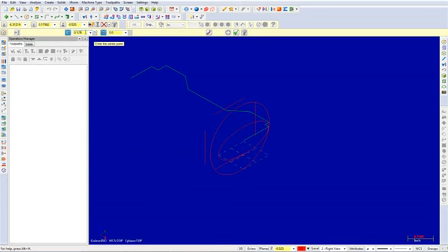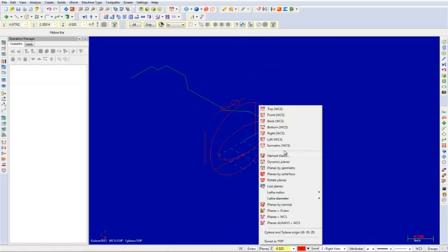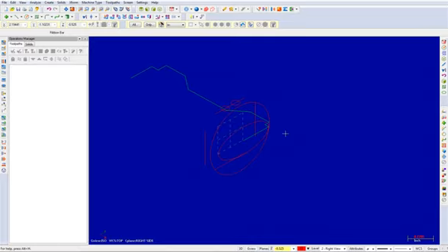Click on the diameter icon to lock this value as shown. Locking this value allows us to create multiple entities of this size. Then pick the 2 line endpoints as shown and select the OK button. Now pick planes from the status bar and select Right. This will keep the graphics view set to isometric and change the construction plane to right.